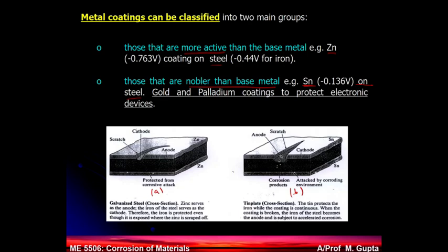Also zinc forms a stable oxide layer, and their inherent reaction with the environment is very slow when compared to iron. So they are the two types of coatings which are used on iron. Zinc is more anodic and tin is cathodic. But the first situation is you cover your two steel samples of the same steel, one with zinc and one with tin. Which one do you think will corrode more, or both of them will show the same rate of corrosion?